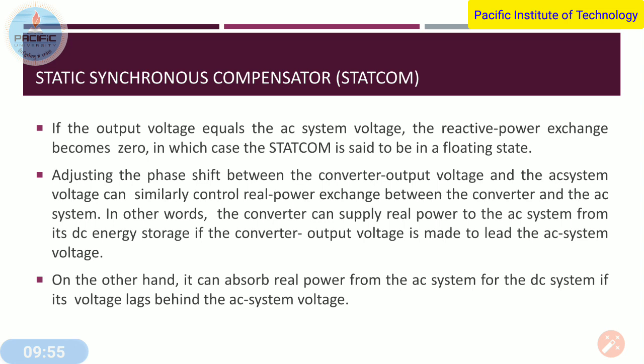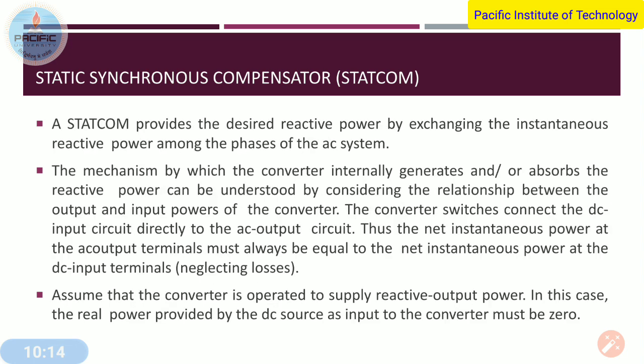If the voltage of the converter is leading, then it will inject real power into the utility system, and if its voltage, that is the STATCOM voltage, is lagging behind the utility voltage, then it will consume real power. So the STATCOM provides the desired reactive power by exchanging the instantaneous reactive power among the phases of the AC system.